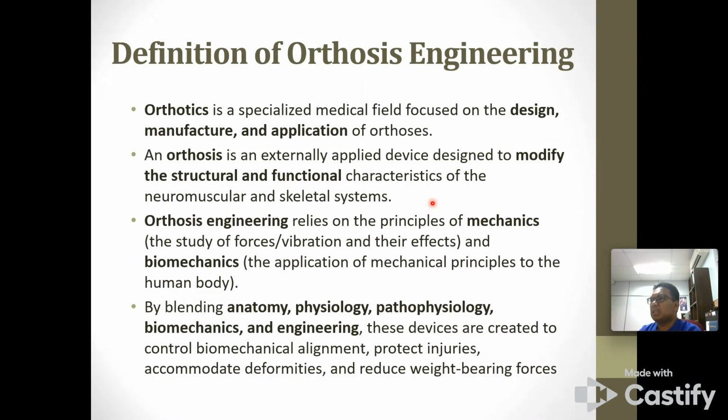When there is interaction between the drill and the wall, specifically when the wall is built of hard material like concrete, vibration may be transferred to your hand, which you do not realize, but in the long term there will be a significant effect, what we call hand-arm vibration. This will be covered in the next lecture.